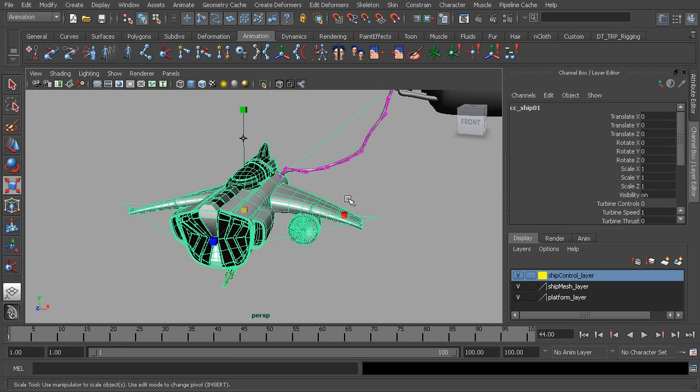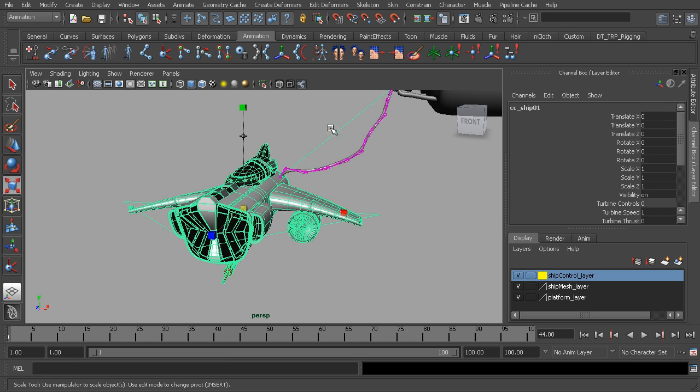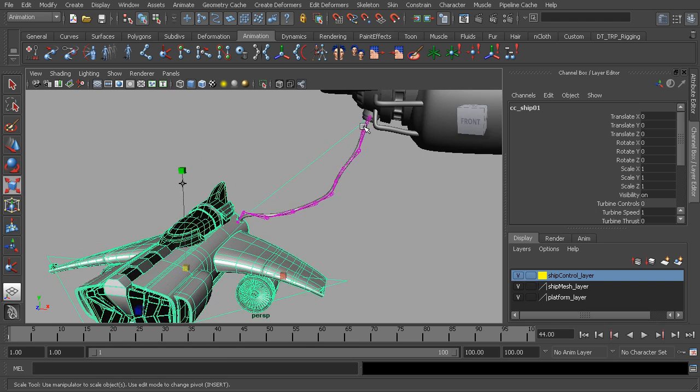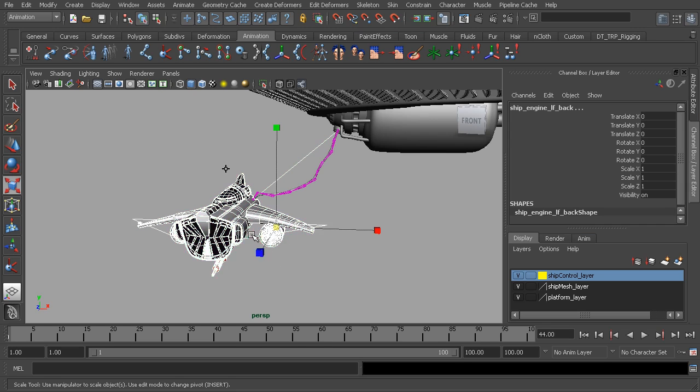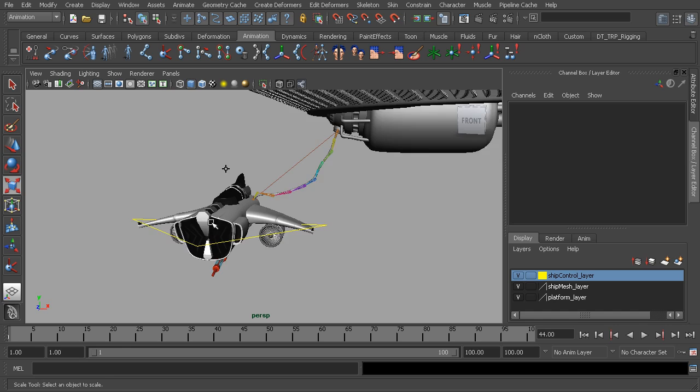We'd also want to remove anything from the scene that would be a distraction, so any joint objects that we won't animate directly should be removed. Same thing goes for our IK handle. And then we'd want to lock down our mesh so that we can conveniently go in and just grab our animation control. So right now we currently cannot do that at all. So let's go ahead and get started.